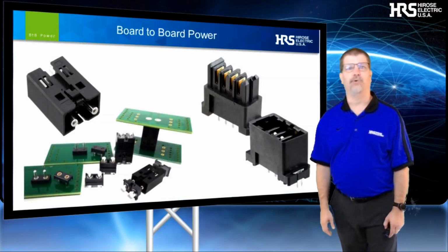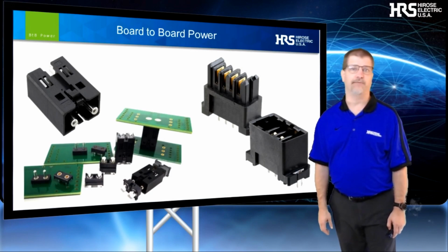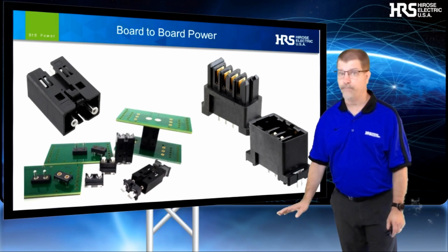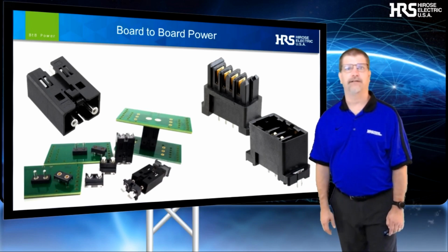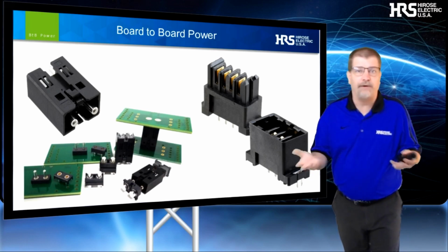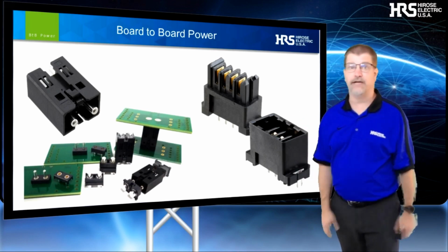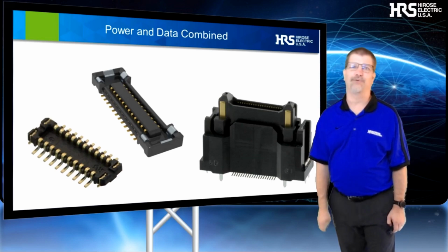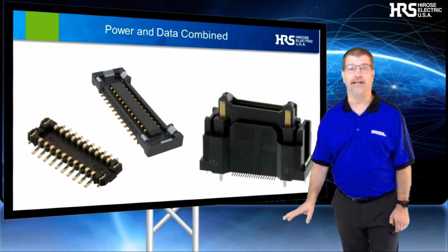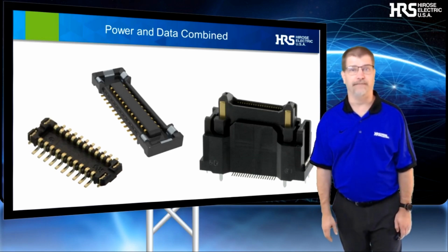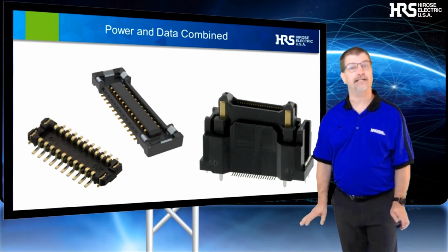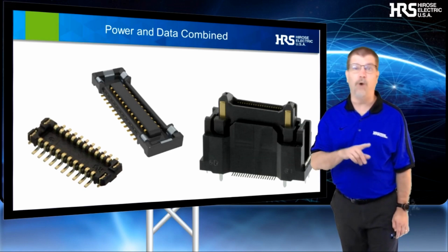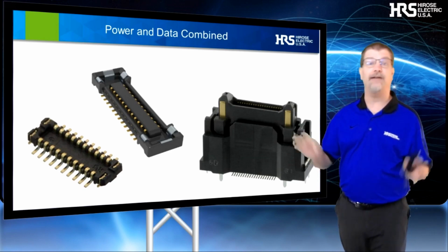Finally, I want to mention board-to-board connectivity as it relates to power connections. Traditionally, these connections were either data or power, but not both. Designers would combine contacts together when they needed to deliver more current than just what a single contact could handle. Today's board-to-board connectors offer many choices for combining power and data into a single connection. This improvement allows you to gain space savings and reduce complexity in your design by only using 1 or 2 power contacts instead of 10 or more.